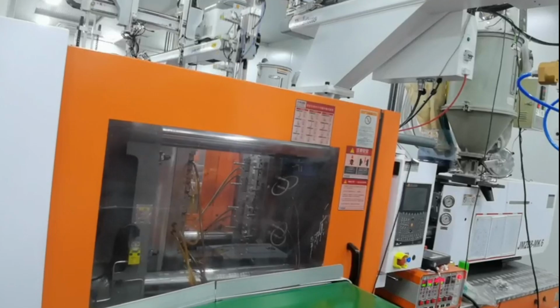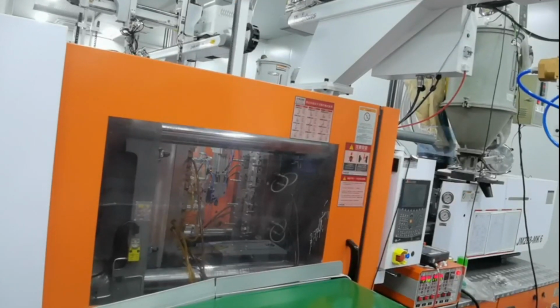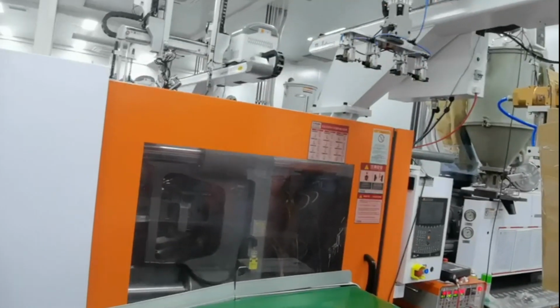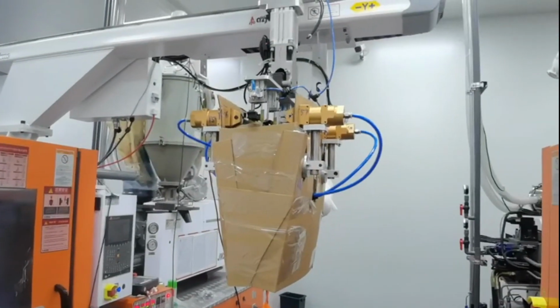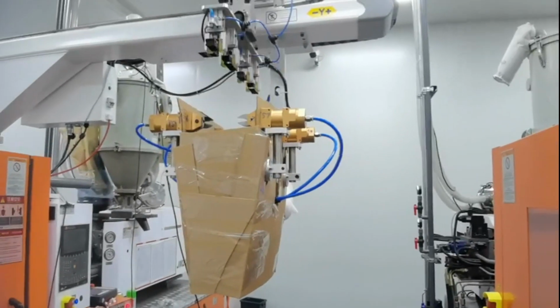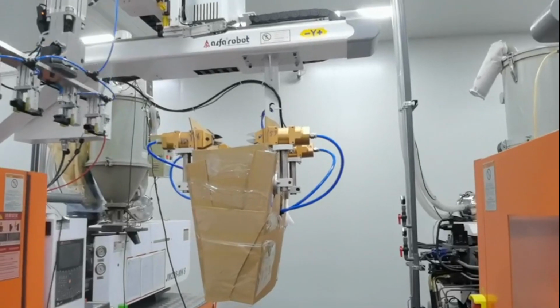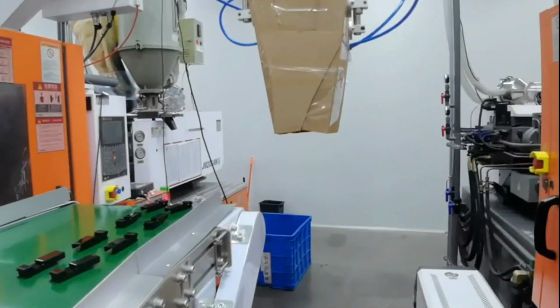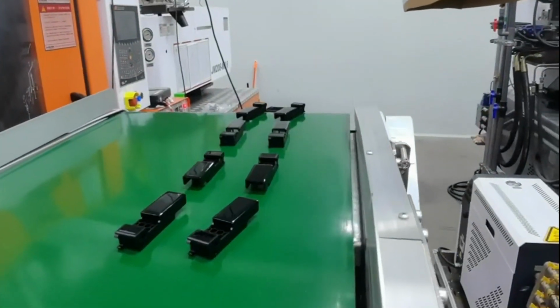Once the plastic product has cooled to the proper temperature, the product can be removed from the mold. The mold is opened and the plastic product is ejected from the mold cavity by an ejector mechanism. There are various types of ejection methods, such as mechanical ejection using ejector pins, ejector plates, etc., and pneumatic ejection. The demolded plastic product is removed from the injection molding machine for subsequent processing, such as trimming the gate, inspection, packaging, etc.